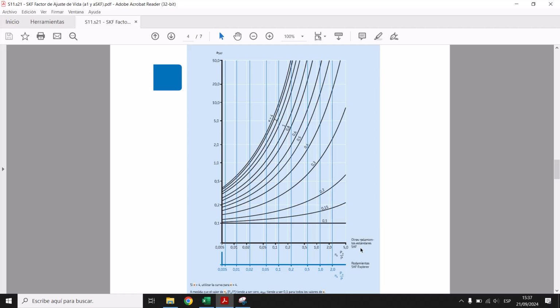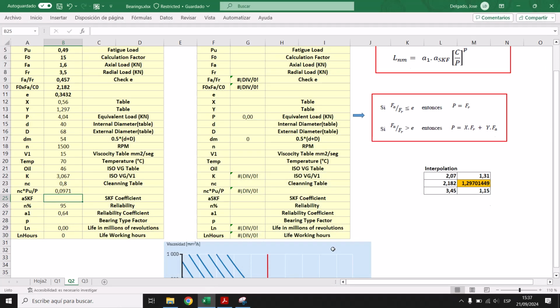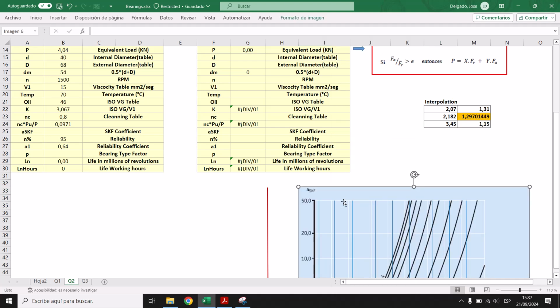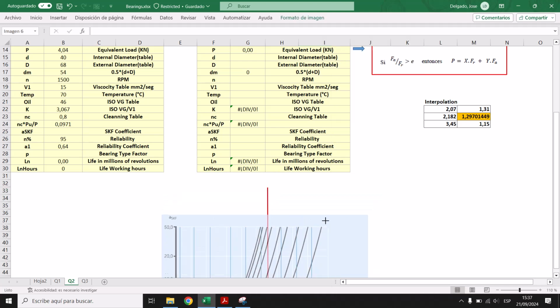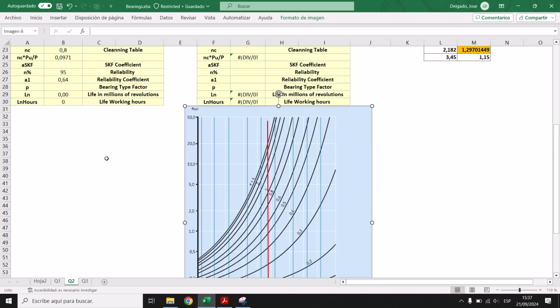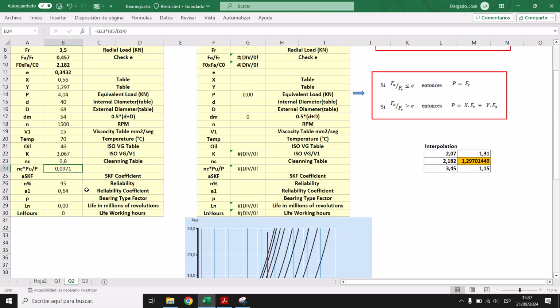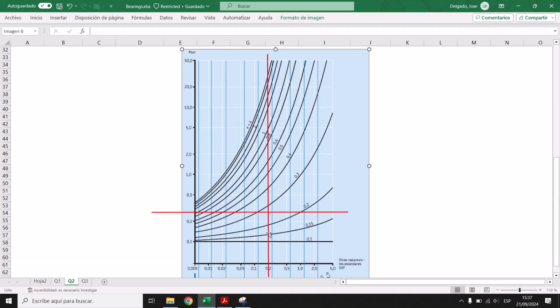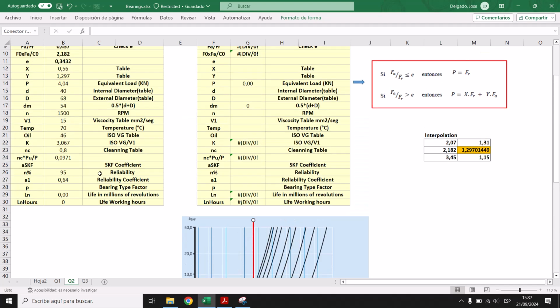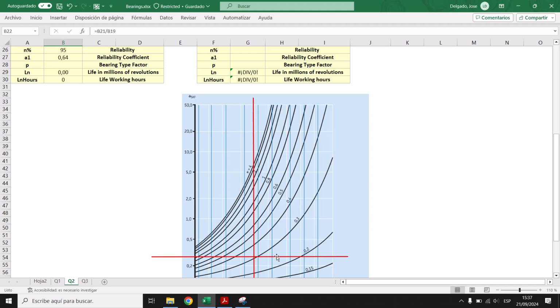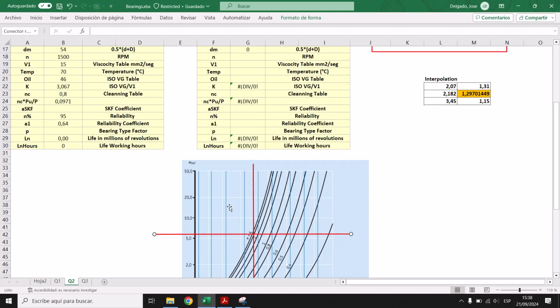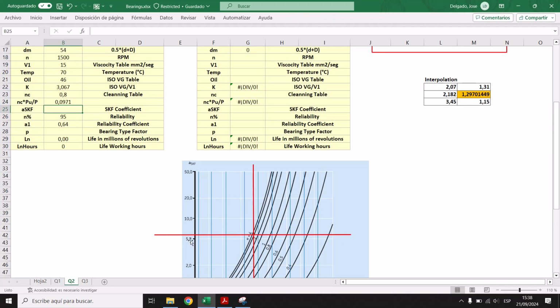If you have other bearings, let's use the information. We don't need this, so let's change it. Okay, this is our entered value. As you can see, 0.09. So we are almost here, 0.09 maybe. And for K, we have 3.076703. It's almost here. What value should we put here? Because we are in the range of 5 until 10, I'm going to use 6 maybe.